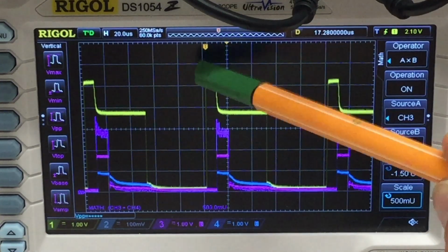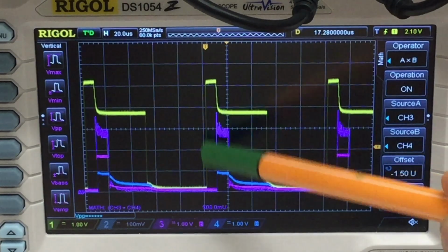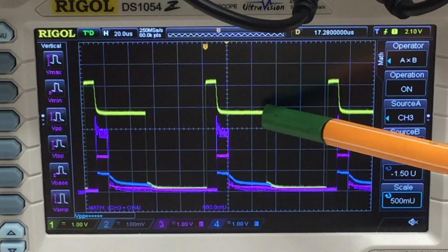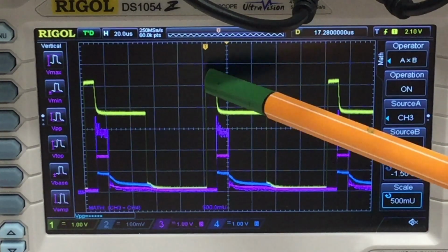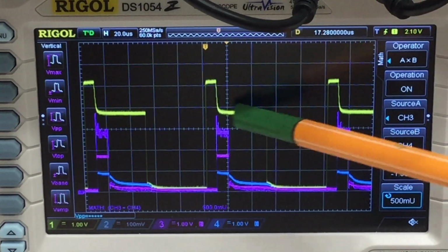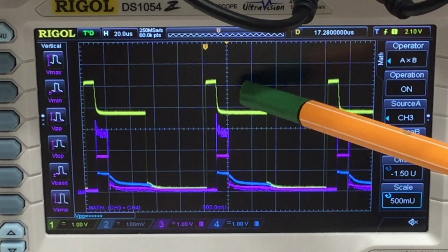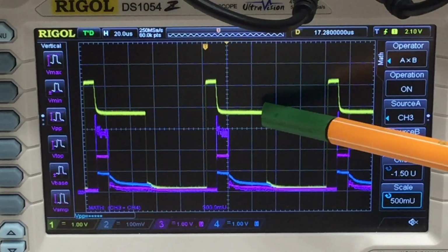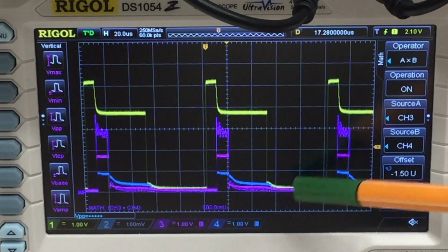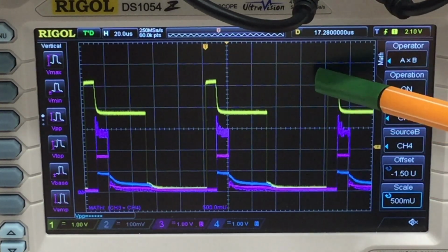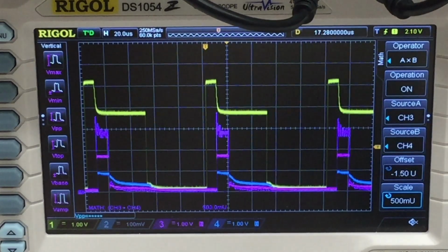The voltage to main terminal 2 rises, and then the trigger impulse is applied. And then we have a voltage drop here, which is not the 100 ohm resistor. That probe is just before it. That is the drop across the 50 ohms output impedance of the function generator. And then my square wave returns to 0, and my TRIAC goes back into the off state until the cycle repeats again. Now let's zoom in a little bit.